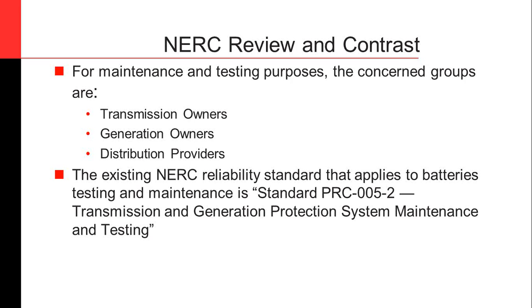So again, this is not an in-depth NERC review. Just wanted to highlight a couple of things. Obviously, the NERC standards are for basically anybody touching the transmission grid, so transmission owners, generation owners, distribution providers. And the current standard that applies to battery testing and maintenance is PRC-005-2. You can just do a Google search for PRC-005-2 and it'll pop up. It's on the NERC website, and the title is Transmission and Generation Protection System Maintenance and Testing.